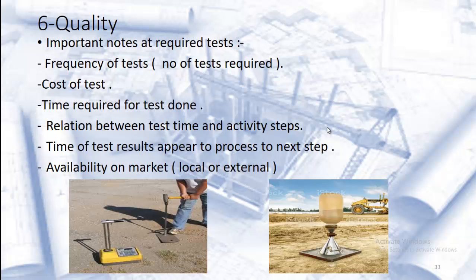Other tests like the non-working pile loading test, which we do to check the assumption of pile load, must be done before starting the work. So this point is important to take into consideration in the cost, the time and the schedule of the project. Also the time for test results to appear, to proceed to the next step.